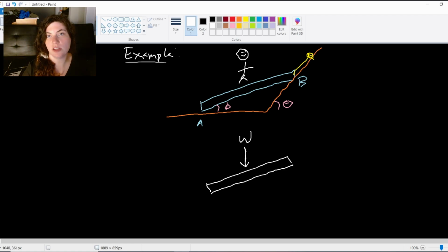I'm just going to label it W because that's the thing that makes the most sense. As long as you make sure that all of these forces have labels, whether they're numbers or names, all of the forces need to have these labels. So we have our man's weight on here. Then we have our quote-unquote reactions at A and B. And these are really normal forces, right? These are just the walls pressing up against the board. So at A, we have this normal force from the floor pushing up against the board.